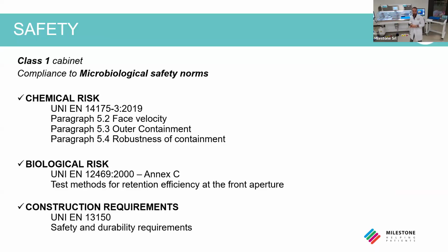Behind me, we do have a class 1 cabinet, but compliant to some microbiological safety norms. In particular, we are compliant to several paragraphs of several norms that you see on the screen. So the UNI-EN 14175 regulates the face velocity, the outer containment, and the robustness of containment of the system. Then we are compliant to Annex C of the UNI-EN 12469, which regulates the retention and efficiency of the